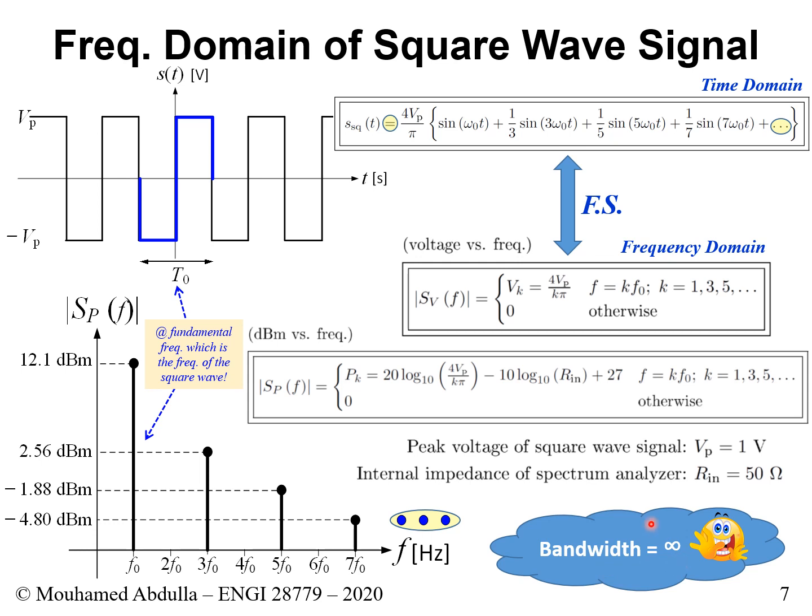So certainly, the more harmonics we add, the better it will look in terms of this signal. It will look closer to what this signal is. So this is one advantage of having a large number of harmonics, is that it will look closer to the actual signal. But the key disadvantage is that the bandwidth will go to infinity. So this is where you have a trade-off. You want your approximate signal with Fourier series to resemble the actual signal, but you do not want to deal with infinite